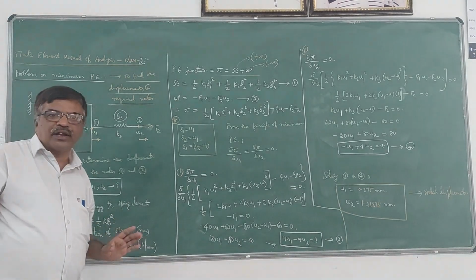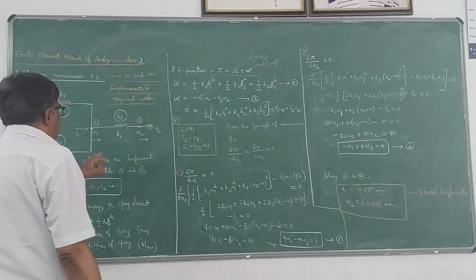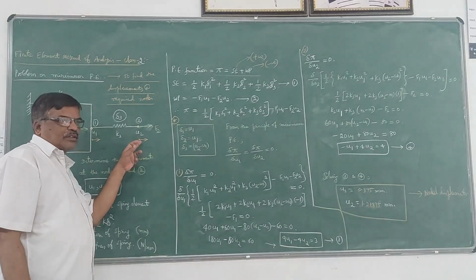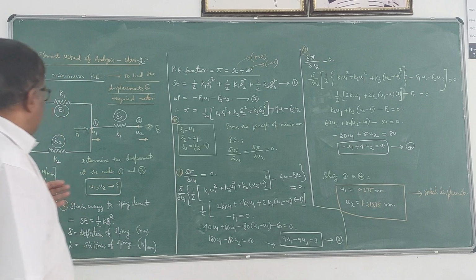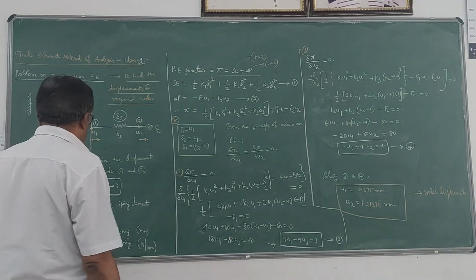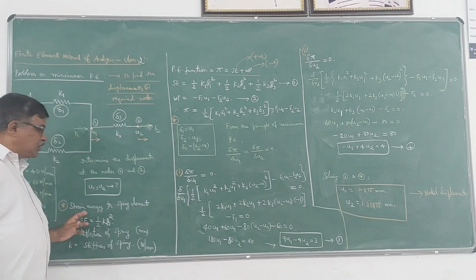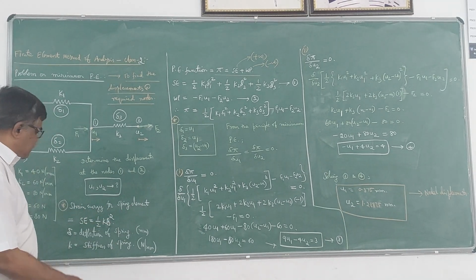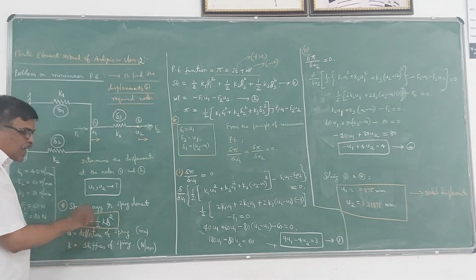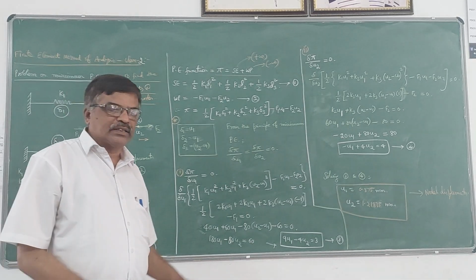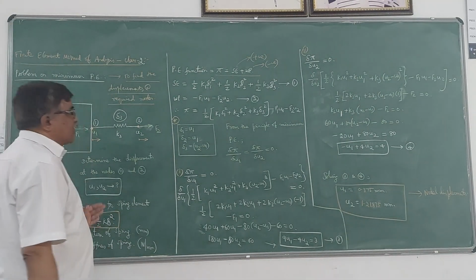Now this problem we can solve. So now we need to find the nodal displacements U1 and U2, which are subjected to the forces F1 and F2 with the spring systems K1, K2, K3. Now, for that we need to know the formula to find the strain energy for the spring element. Strain energy for the spring element is given by half into K into delta square, where K is the spring constant and delta is the deflection in that particular spring.